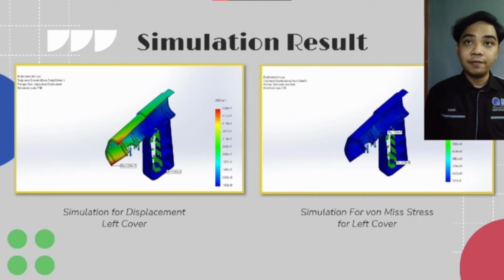This is because the force was taken from the assumption of the liquid inside the bottle, which is 380 milliliters. If we take the density of water, which is 1000 kilograms per cubic meter, we get a force of 3.7 Newton. By considering the materials involved in the parts, for example the bottle holder, bottle, rubber divider, tubing and anchor, we take 5 as the force.